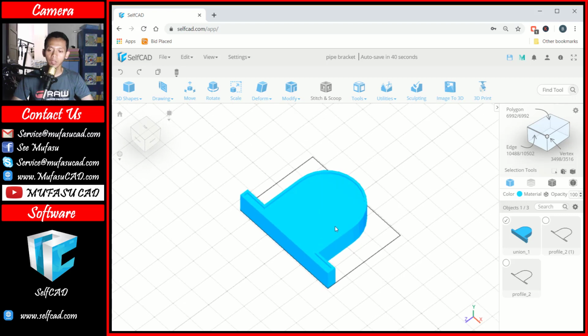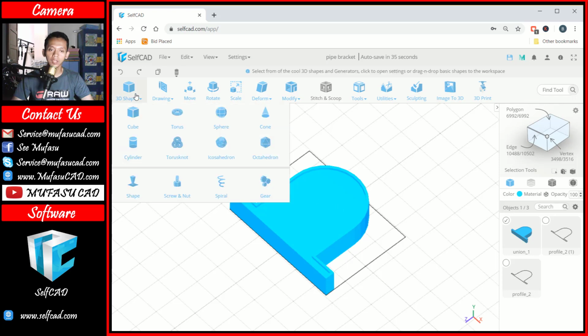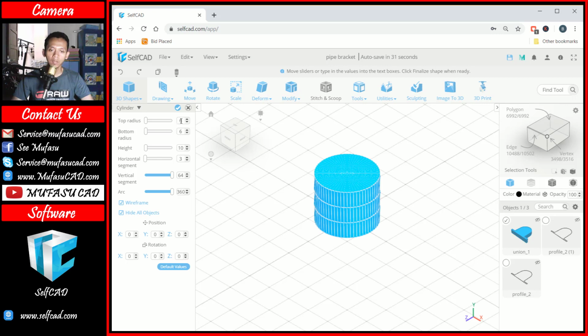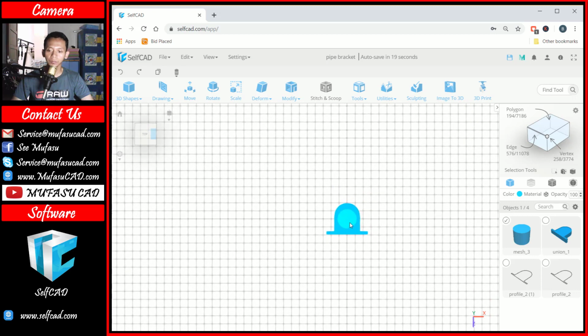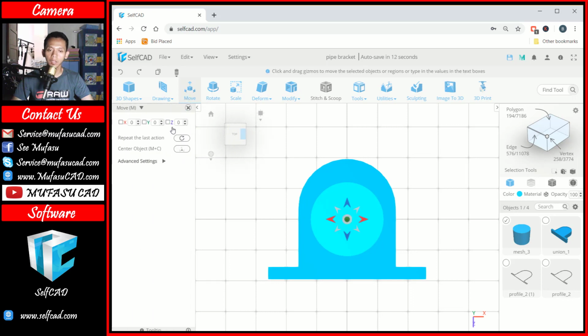And next to create a hole we can create a cylinder object. Okay, I will click 3D shape and click cylinder. In here for top radius I will set it to 6, bottom radius 6, okay, and height 10. You can click OK to apply. And then I will change into top view. You can zoom in. Okay, we can use the move command to move this object. Okay, I will move in Z axis into -2 and you can close.